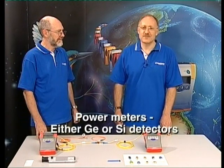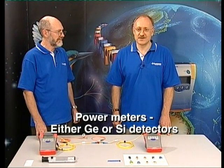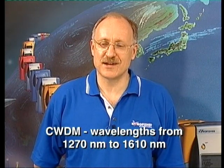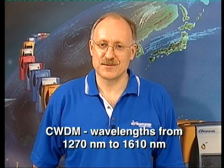Multimode testing is generally less accurate and repeatable. It uses LED sources at typically 850 nanometers and 1300 nanometers, and power meters using either germanium detectors or silicon detectors. Indium gallium arsenide detectors do work, but are very inaccurate at 850 nanometers. More advanced DWDM or CWDM systems use other wavelengths from 1270 nanometers to 1610 nanometers, and may be of either fiber type.